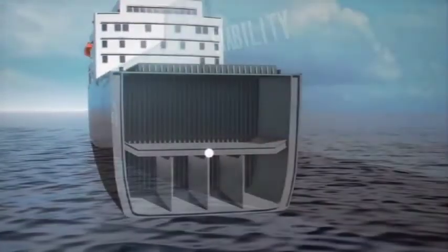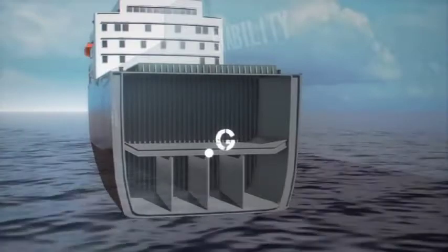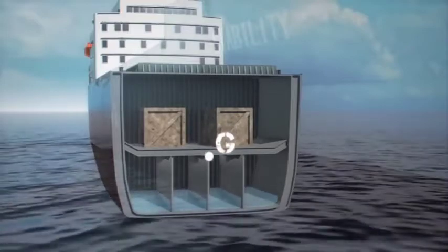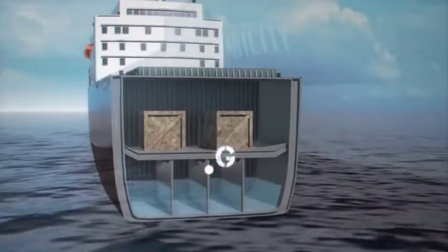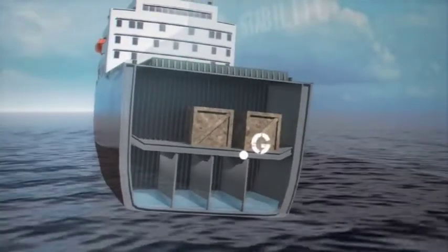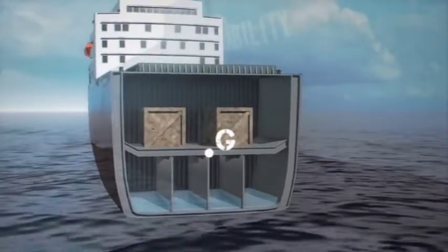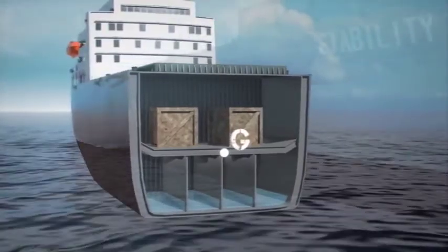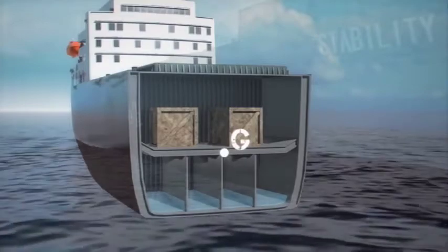The center of gravity, or G, is the single point where the downward force of gravity acts. The center of gravity is the combined effect of the position and weight of everything on board a vessel. The center of gravity moves toward any added weight, away from any removed weight, and in the same direction as any shift in weight. On a properly managed vessel, the center of gravity should be maintained on the center line for maximum stability.